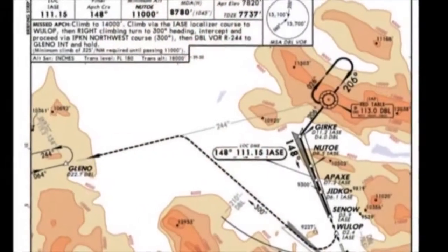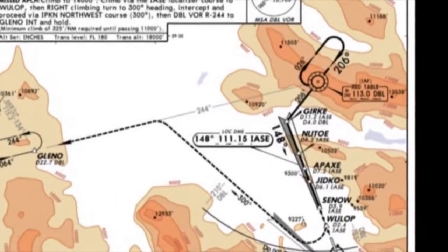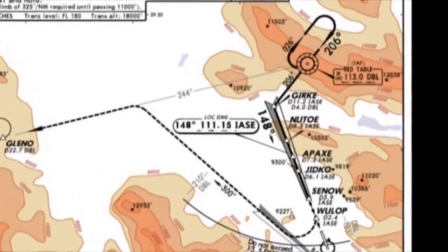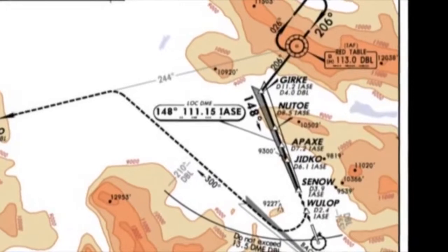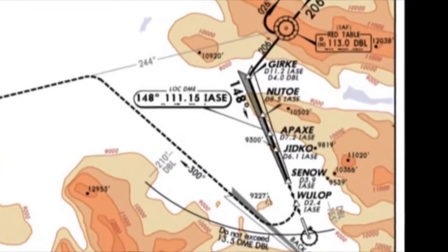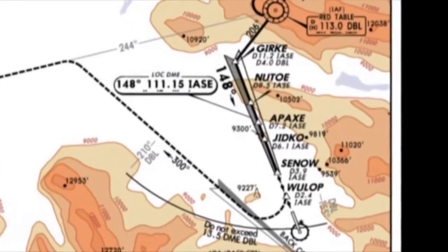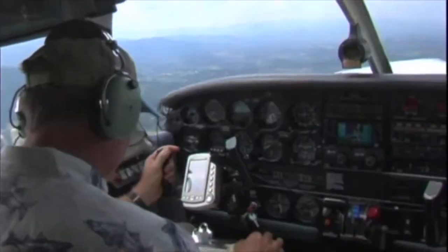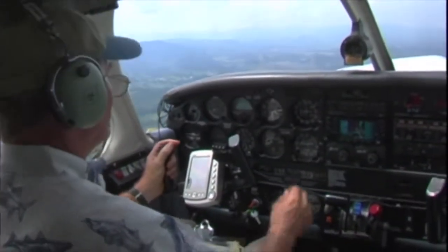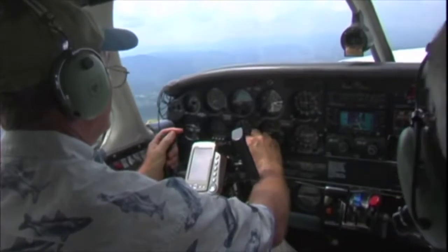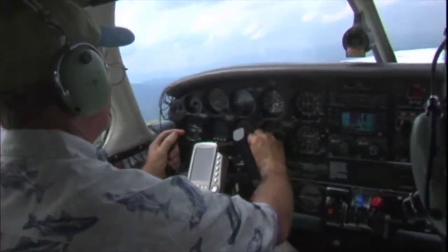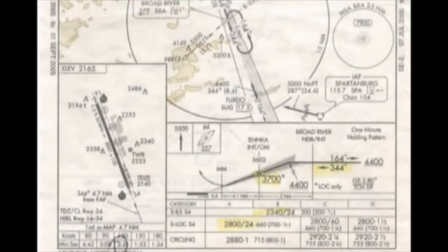Just because it's a published approach does not make it perfect. Airports with poorly designed approach procedures contribute to an environment where controlled flight into terrain is possible. And even a perfectly designed approach is a hazard if not perfectly flown. Each published altitude on an approach has a specific purpose. Key fixes and airport elevation must be noted and associated with terrain and obstacles along the approach path.